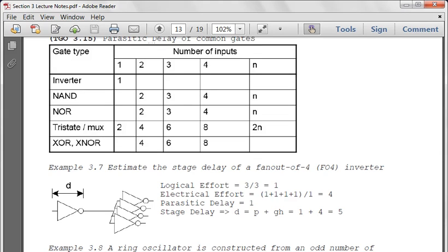So we're now combining concepts. We have poly driving the poly input to each of these inverters, and then you have your PMOS and NMOS circuits. You have to be able to create the channel, depending on the supply voltage and ground, to each inverter. And in order to do that, you have to supply that voltage to each and every one to be able to create the current. So that's why you worry about this concept of stage delay.